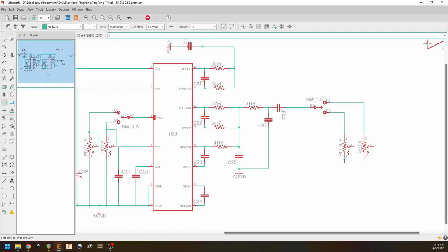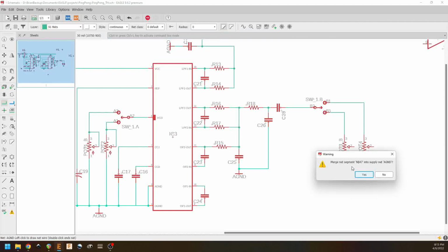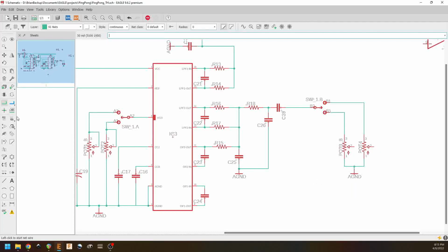Okay. And then I'm going to connect these guys both to ground. I'm going to give them their own little ground symbol over here, because we still have to put in the feedback pot, and I don't want to be crossing my nets on my schematic any more than I have to, just to try and keep it clean. There we go. We're going to save real quick.